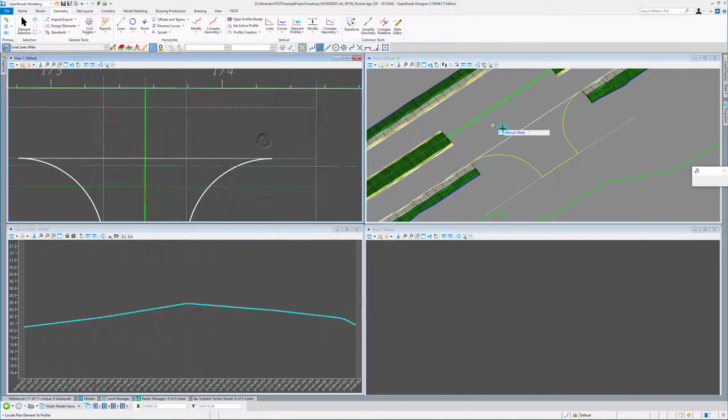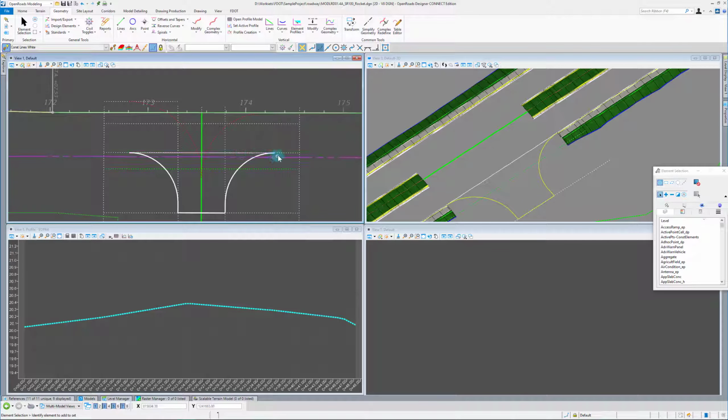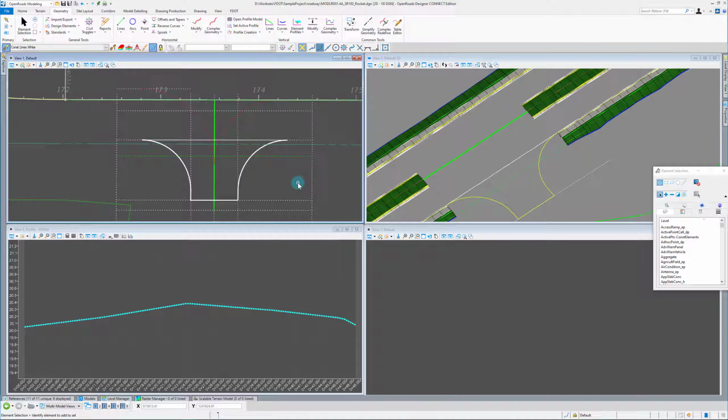And so what that'll do is now we have a line that is ruled to the line underneath it. So it's just going to follow this profile. So if the profile on this line changes, the profile on this line changes. And as you can see as we're building this, this line right here is kind of dictating our entire curb return. So this line profile, which is pulled from our projected pavement, is kind of dictating the profile along here. The existing ground isn't going to change. The only reason it would change is if we decided to change this offset for some reason.